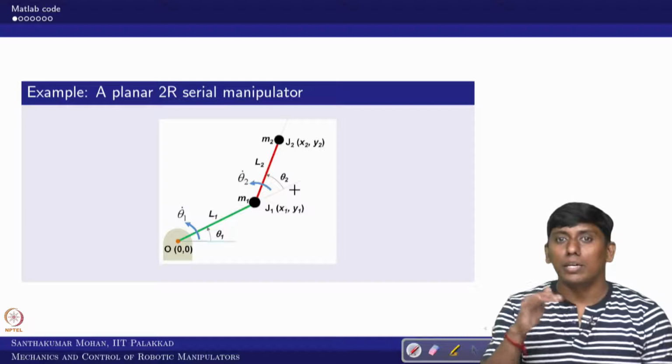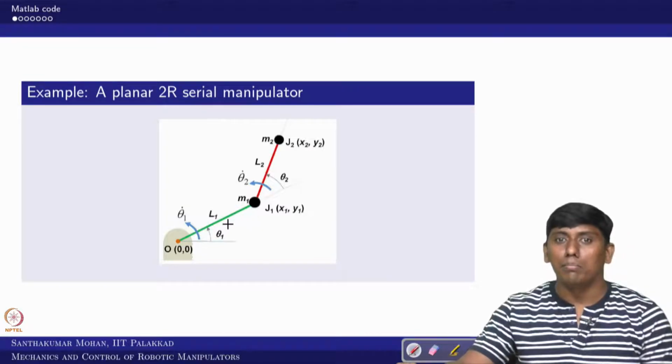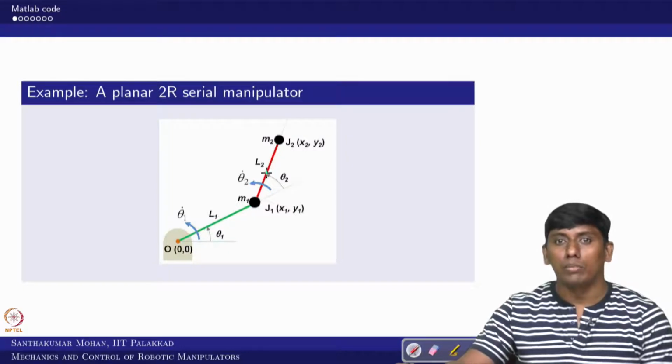What we now require is the centroidal location. In this case the link 1 mass is concentrated at the point J1, the mass is M1 and there is no inertia, it is a point mass. Similarly, the second link mass M2 is concentrated at the J2 point. If you recall your frame arrangement, along L1 is assigned the x1 axis, and along L2 would be the x2 axis.